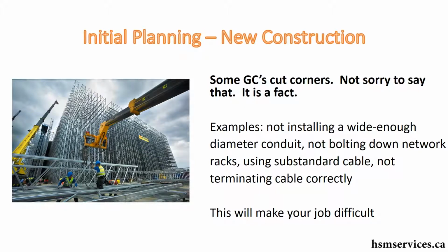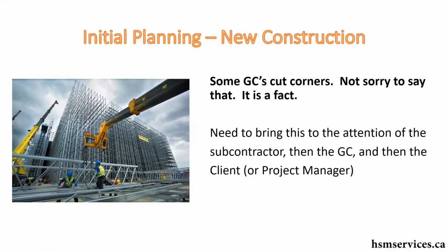So how do you prevent that? Well, you need to be on site, and you need to be inspecting things during the construction phase and communicating with the contractors and with the GC and with the client. So if something isn't being done right, you need to explain to people it has to be redone properly. Otherwise, it's not going to work. Put everything in writing. That helps with your warranty in case there's a dispute later.